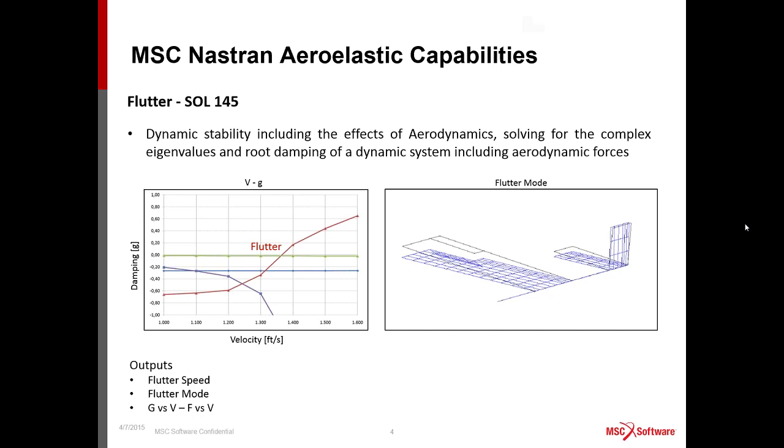Something that is interesting is even to evaluate how the frequency of the elastic system changes with respect to the velocity, and we can even process in post-processing the flutter mode and animate it, in order to see which structural modes are coupled in the aeroelastic mode.